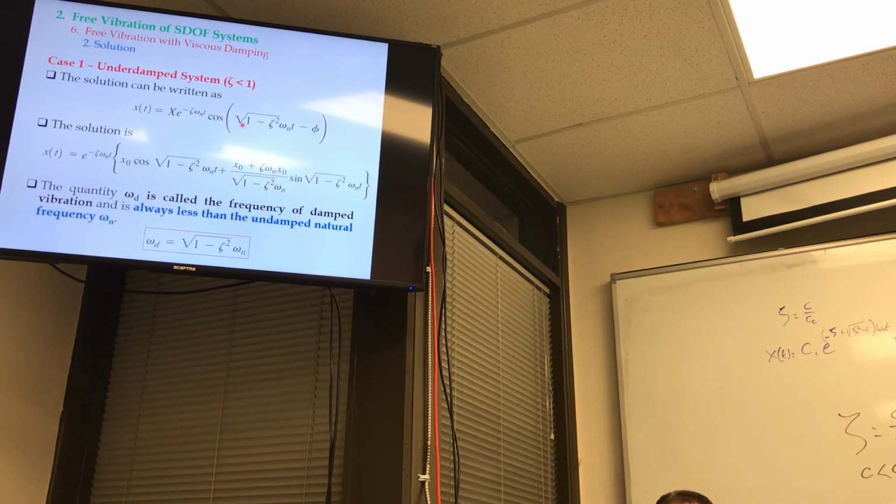So if we were to apply that equation to an actual scenario, and we solve for x of t, what are we going to get, like in terms of units? How would you take this and apply it to an engineering scenario? Well, let's say you're applying it to the simplest possible case, a mass that is attached to the end of a spring and that has a damper on it, okay? The x would be the dimension that you are measuring from the equilibrium position. It's got an initial velocity, it's got an initial displacement.